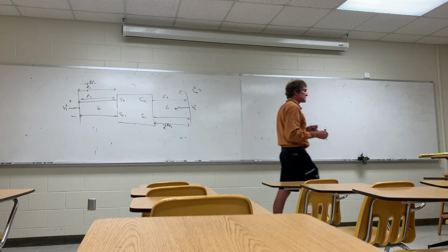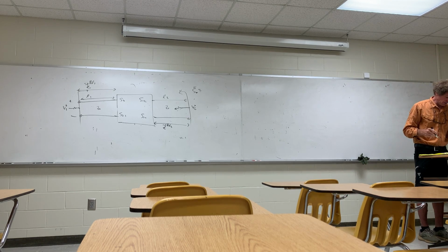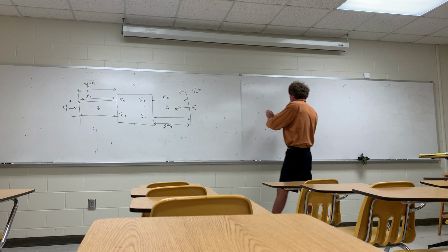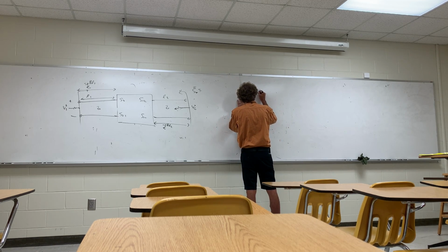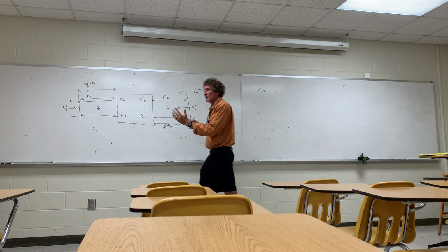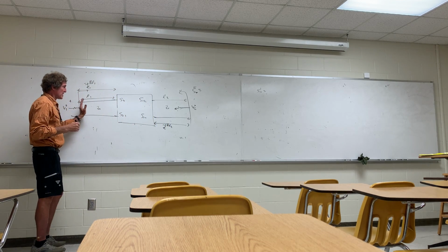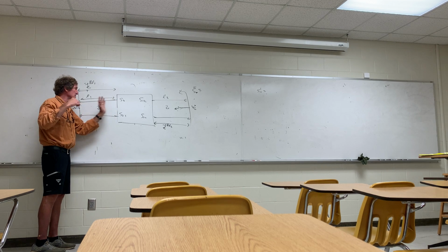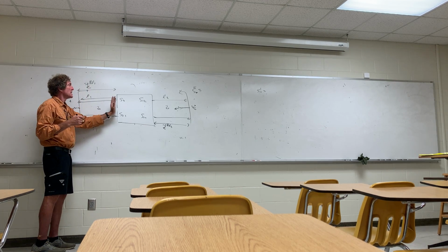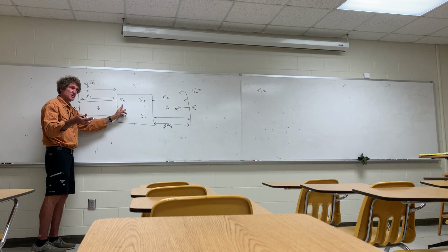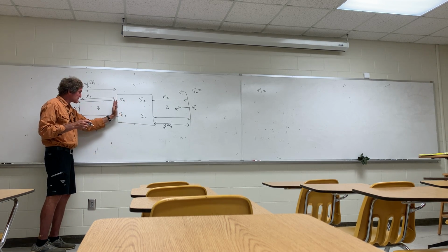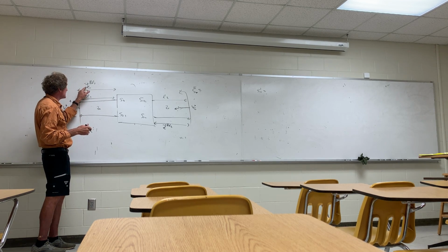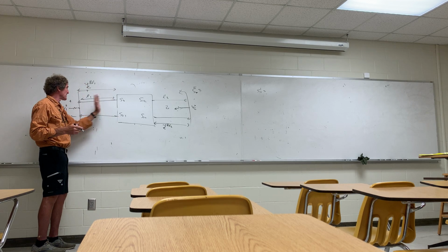And you can almost guess what I'm going to do. When I actually look, first we'll start with the reflection coefficient. When I look at the new S11, I'll call it S11 and I'll just prime it. Now that's going to be, if you think about it, V1 plus comes in here, it comes down and hits here. So now I have V1 plus times the phase shift e to the minus j beta L1 times S11, because that is the reflection coefficient, given that port 2 is matched, right? And then it's going to come back, so you're going to get a total phase change of e to the minus j 2 beta L1 by the time the wave reflects here.